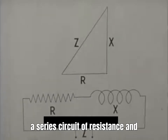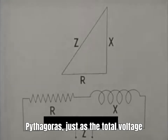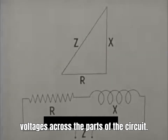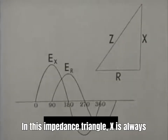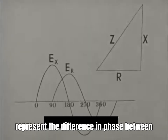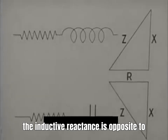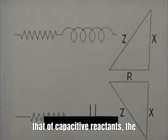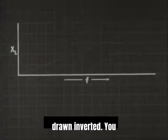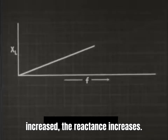Therefore, in a series circuit of resistance and reactance, the impedance to alternating current may be found by the theorem of Pythagoras, just as the total voltage across the circuit can be found from the voltages across the parts of the circuit. In this impedance triangle, X is always drawn at right angles to R to represent the difference in phase between the voltages across the reactance and resistance. Since the effect of the inductive reactance is opposite to that of capacitive reactance, the impedance triangle for the latter may be drawn inverted. You will remember from the study of inductance that as the frequency is increased, the reactance increases.